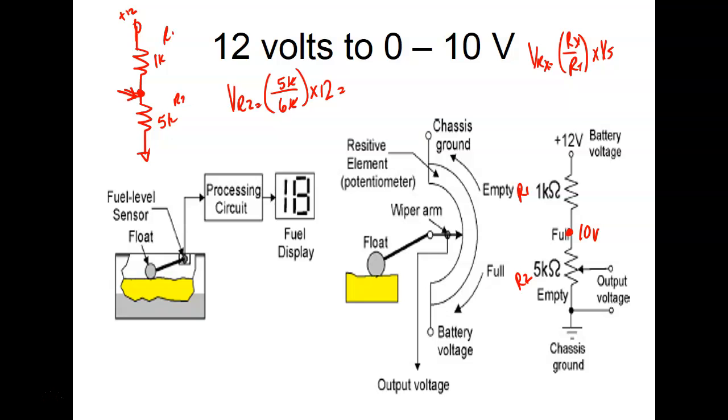What would most of y'all do? You'd recalculate the current again. But this ratio has absolutely no reference to the voltage that's applied to it. So this resistor would drop 5/6 of the voltage, whether you put 20 volts across it, 5 volts, or 8 volts. The ratio of the resistors is never going to change, right?